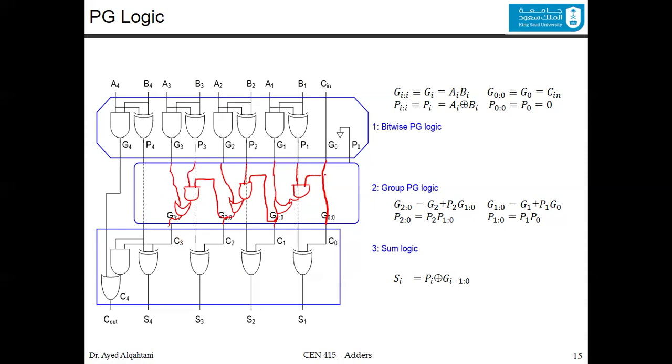And you can see that this is actually really the ripple adder, where you have the carry in going this way, rippled, and rippled, all the way until you get the carry out here. And the same scenario is repeated here. It's either generated at 4, or it is from the previous generation 0 to 3 and propagated to 4 to get the carry out.